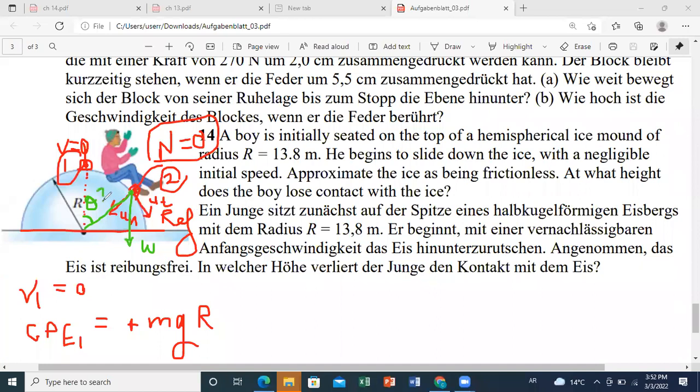The first equation I can write is the sum of forces along un equals m a_n. Because I'm dealing with normal-tangential coordinates, a_n is v squared over radius. So the sum of forces along n equals m times v squared over r.